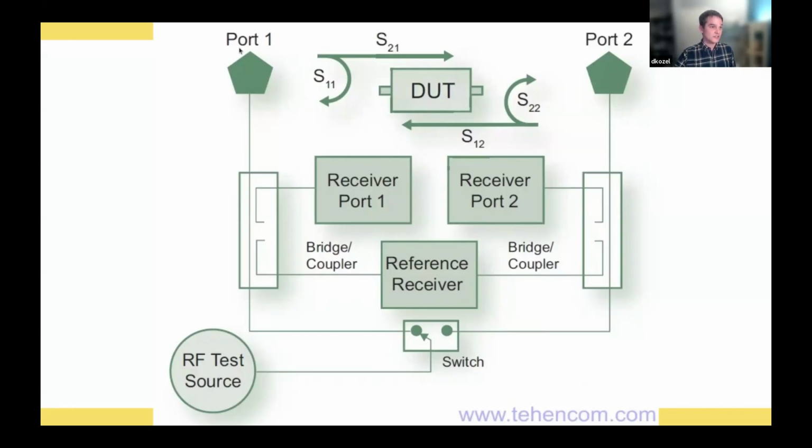And let's say that we attach this just to an antenna. We're not going to be able to measure anything at port 2 because an antenna only has one port. So the only thing that we can measure is the amount of power reflected backwards, S11. So the power will come backwards across, go back, and we'll receive through another coupler power into port 1. And this gives us our A wave and our B wave. We divide the two, we get S11, and we can plot that out. At that frequency, we can tell you how much power went out versus how much power came back.